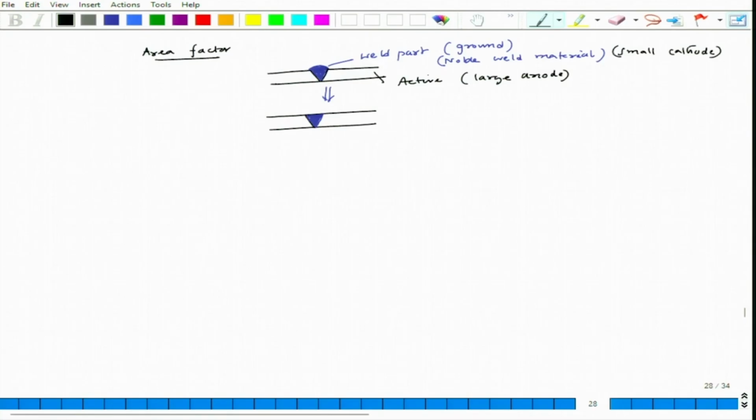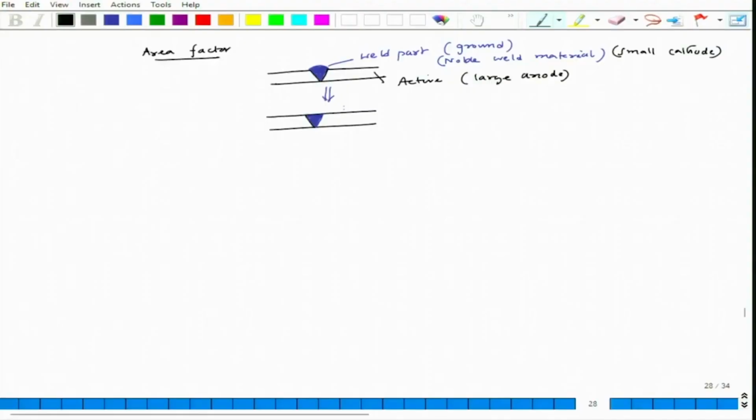And when you grind it, so that means when you try to fix it in a component, there will be matching surfaces. So there will not be much play between the two adjoining surfaces. Let's say this particular surface you are trying to match with another surface. If we have a little hump over it, then definitely it will lead to a mismatched surface. Okay. So that's what the grinding would make better.